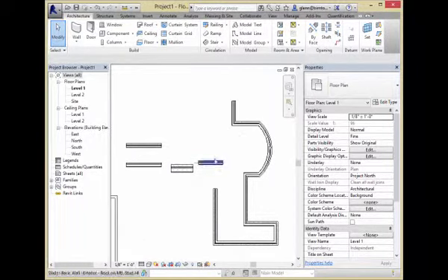So watch this. Hover over a single wall. I'm hovering. Notice I'm not pressing anything. I just have the mouse hovering over that. It says wall, basic wall, and here's the type of wall. If, with one finger, you delicately tap on the tab key, but don't hold, just tap, it's going to rotate through and say, oh, well, you didn't want that.